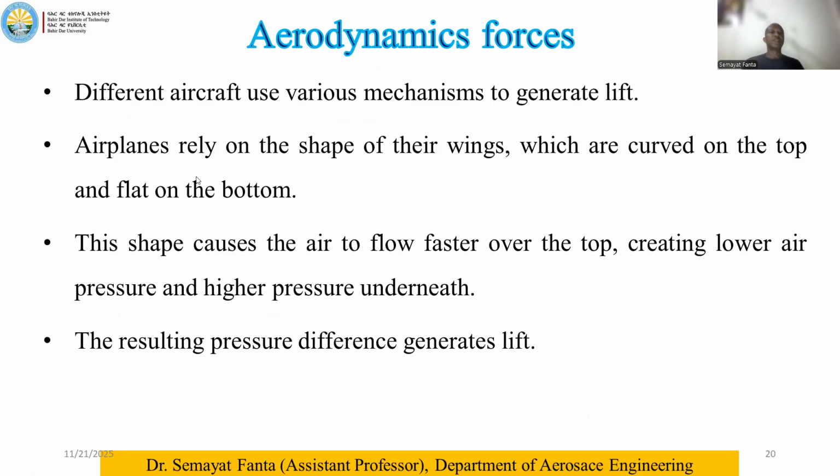Different aircraft use various mechanisms to generate lift, and the airplane relies on the shape of its wings, which are curved on the top and flat on the bottom. So this is what we call, one is a symmetric aerofoil and another is a curved aerofoil.